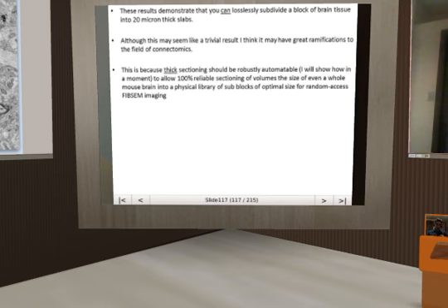Now, that's easy to do if it's a small block, because the region at which this beam is 10 nanometers in diameter is pretty small. If you try to make a 10 nanometer wide ion beam that's, let's say, 1 millimeter in length, it's impossible, because the ions actually push each other away.